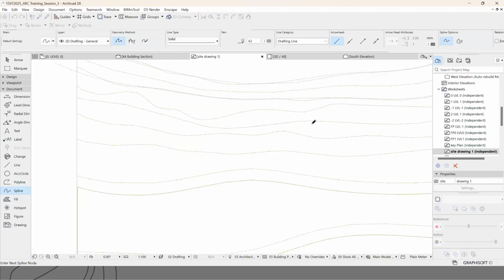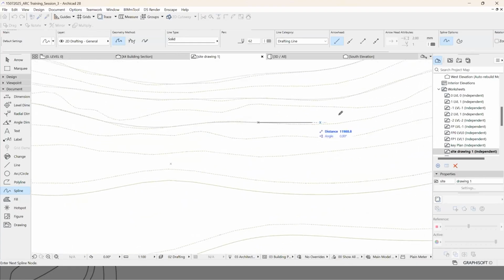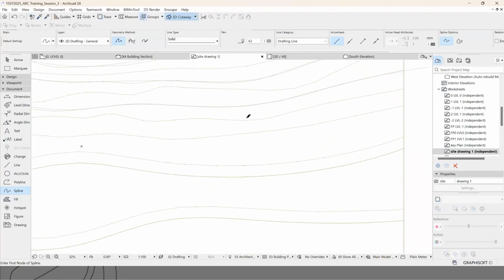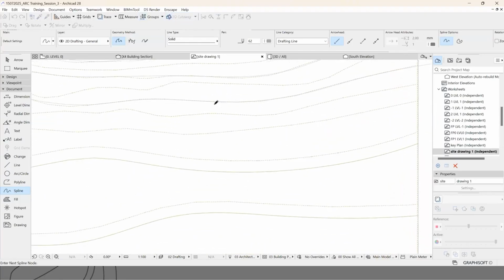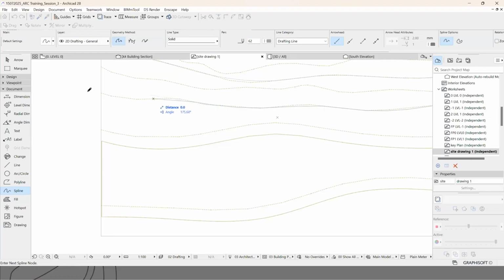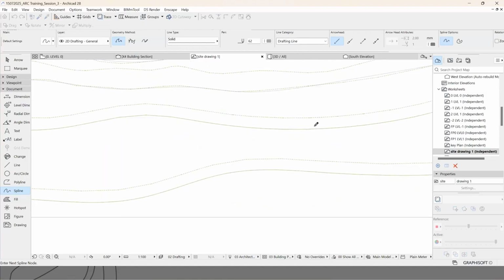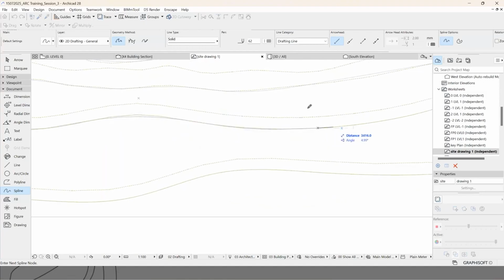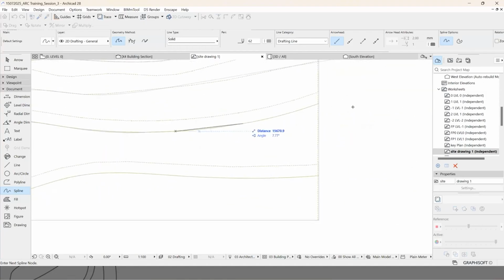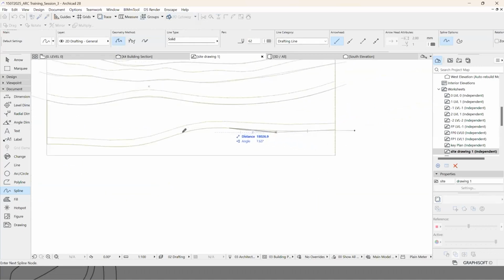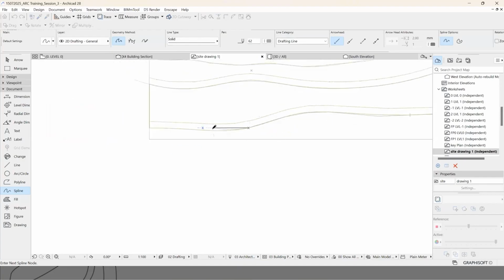This method is done, like I mentioned, only where if your lines are not proper, you can approach it. Otherwise, I will always encourage have a good CAD file and import it and check whether it is broken or not. If it is not, you're good to go. So let me just draw this. I'm taking also a little extra so that when I use the magic wand tool, it takes properly. This is also something that you can keep in mind.